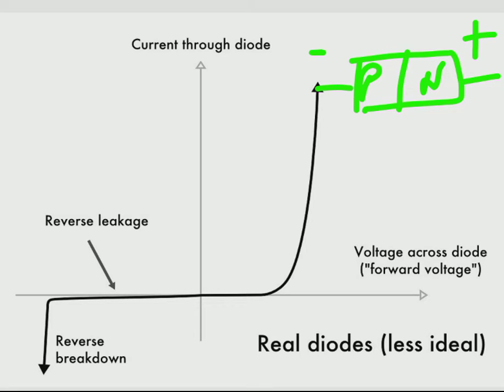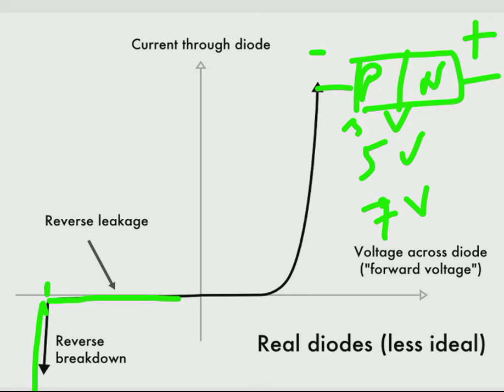In the case of a Zener diode, when you have a reverse voltage, the breakdown happens when that voltage exceeds the breakdown voltage of the Zener diode, which is about, let's say, 5 volt, 7 volt, or even less than 3 volt, depending on what kind of diode it is. When that happens, it conducts current as shown right here, but it doesn't damage the diode, and as the current increases or decreases, it maintains that voltage across the diode.